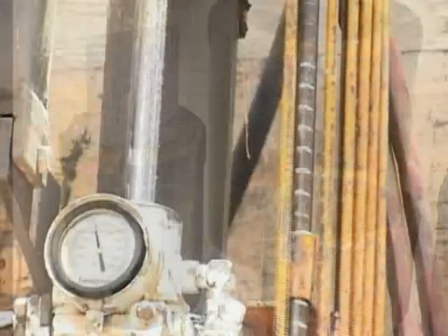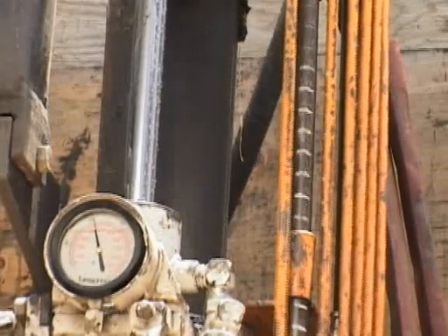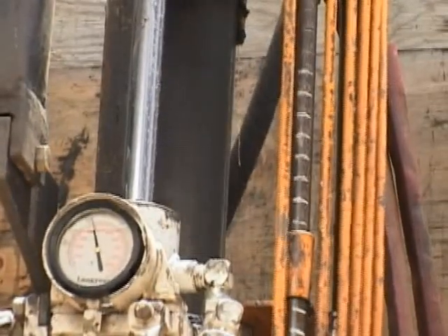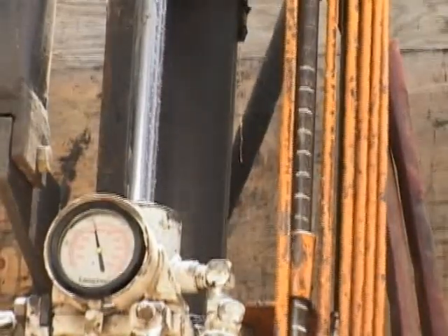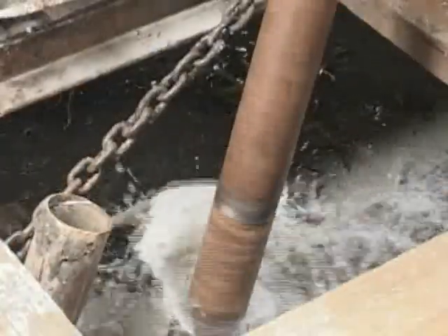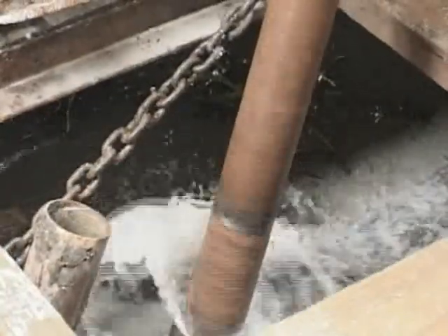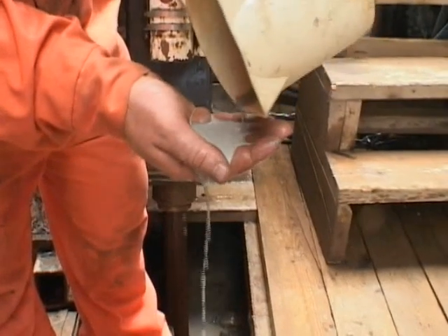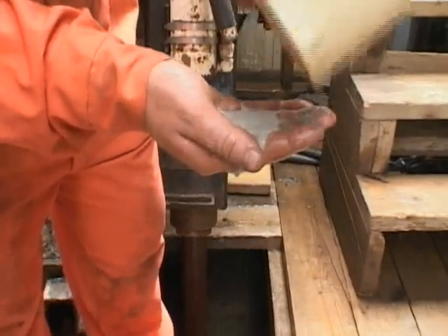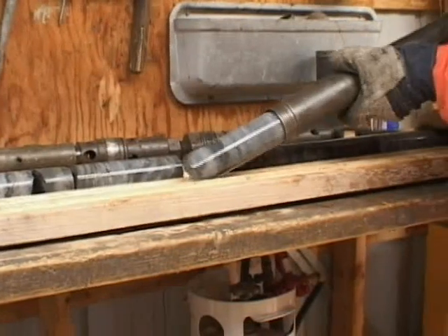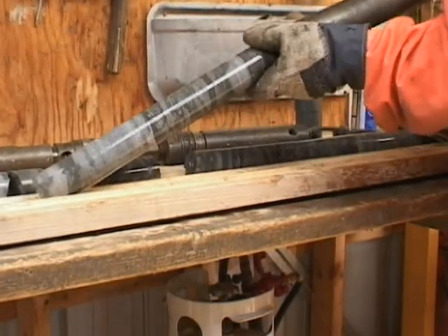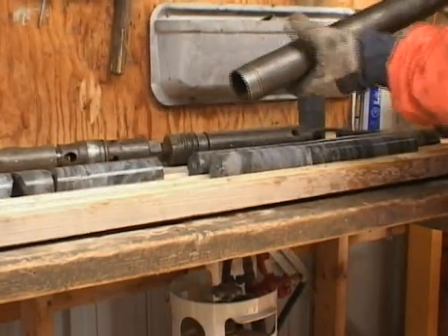To accomplish this, significant pull-down forces are combined with rotation speeds ranging from 1200 RPM to 2000 RPM. These forces are applied to the face of the bit by the swivel head. The water is injected into the rotating drill string to cool the bit and flush the cuttings up and out of the borehole. These cuttings are quite fine and have the consistency of flour. The core sample is contained within the inner tube and is stripped out for evaluation purposes at the end of each run.